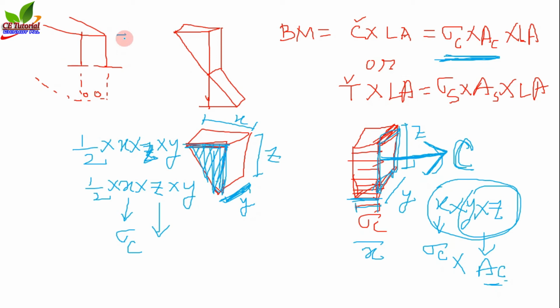If the total height of this beam is d, and I consider the neutral axis depth in terms of d, then we can say that this is kd. So k is a constant, multiplied by d we get this distance, and we need to calculate k. I will show you how we can calculate k.